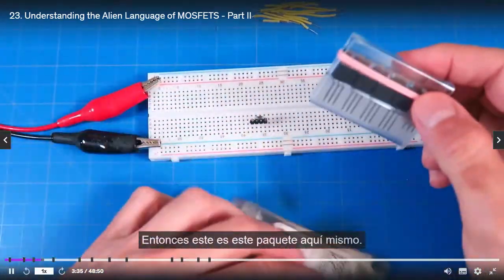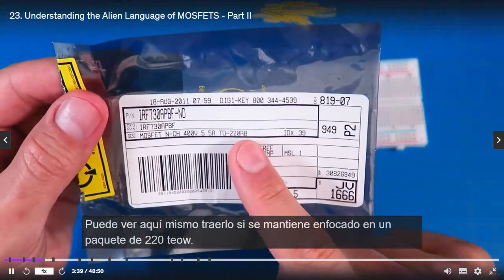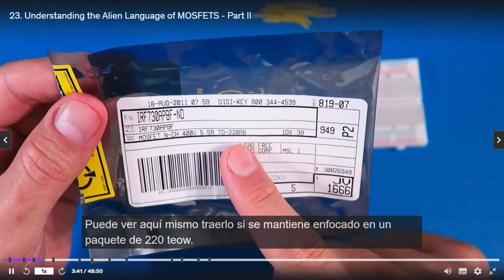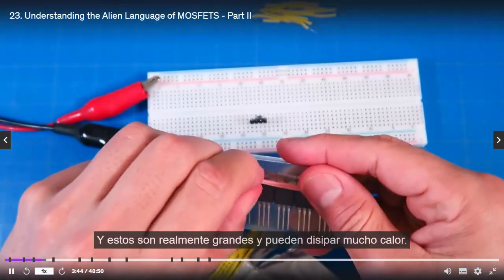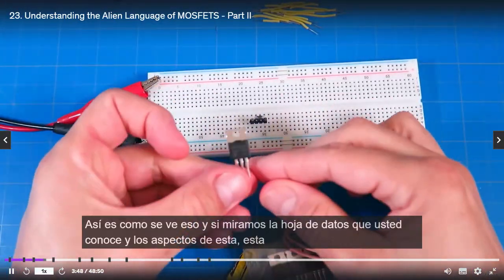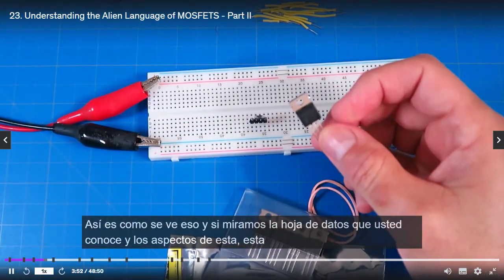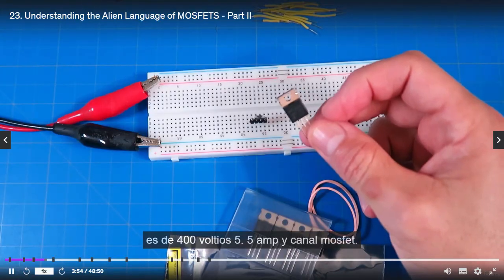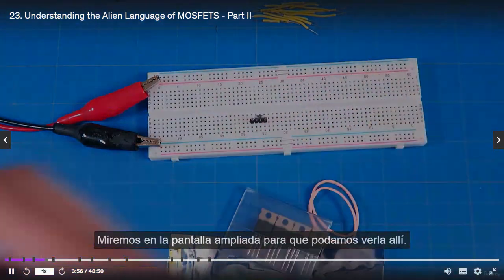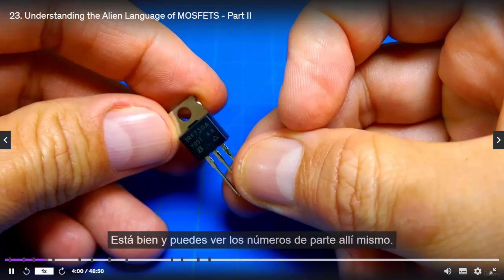So this is this package right here, and you can see right on here, bring it in if it stays in focus, is a TO220 package. And these are really big, and they can dissipate a lot of heat. All right, so that's what that looks like. And if we look at the data sheet and the specs of it, this one's a 400 volt, 5.5 amp N-channel MOSFET. Let's look at it on the zoomed in screen. So we can see that there. All right, and you can see the part numbers right on there.